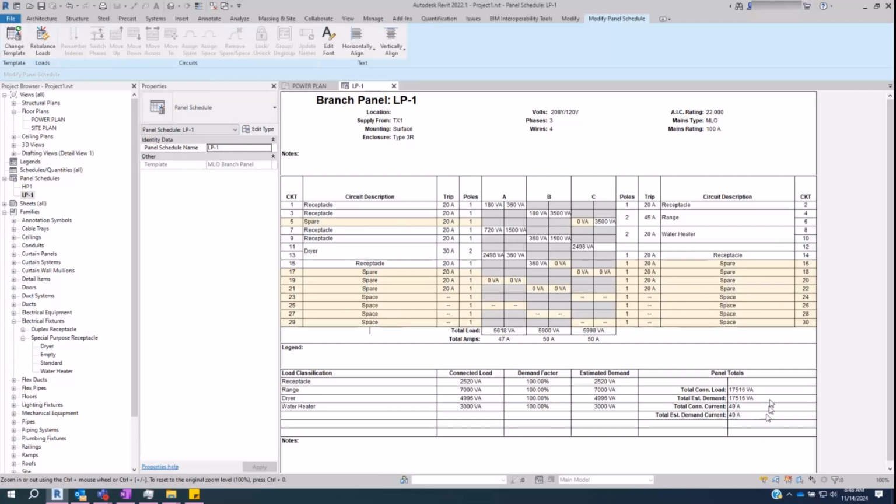And that max number, the 80%, is like you don't want each phase to get over 80 amps. Correct. Okay, because of the upstream breaker only able to handle 80 amps or less for more than 3 hours.